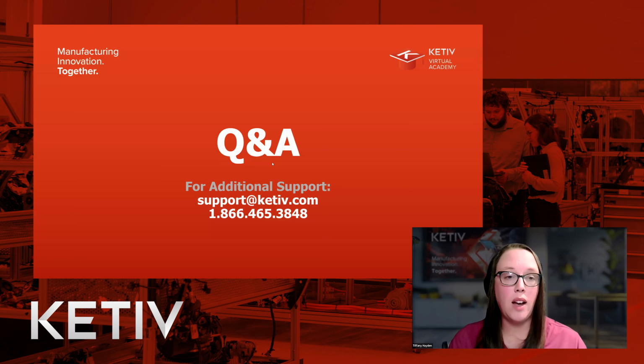But you saw how I brought up some work planes from certain parts up to the assembly level. So that's something that you can do with iLogic. I'll have to dive into that. It's been a while since I created work planes within iLogic. A lot of the times I'm dealing with just standard work planes, so you want them in all the components, but it is possible to add them from the iLogic.